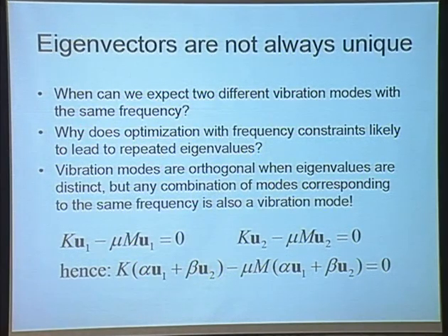Occasionally, you'll analyze a structure that somebody else optimized, and you look at the vibration mode that gives you a problem, and you will not be able to see any physical correspondence, why it is vibrating in this strange way. And if you didn't pay attention to the fact that you have two vibration frequencies that are almost the same, all of your physical understanding of the vibration shape will be lost.